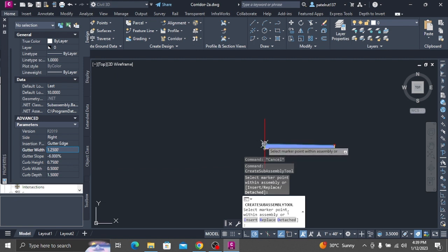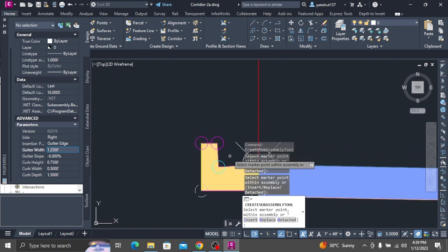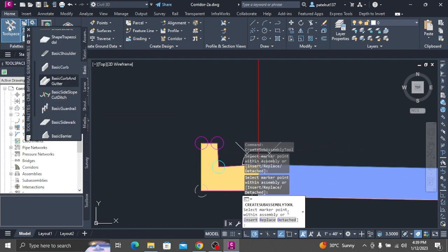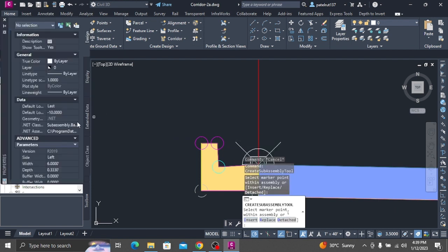Click OK. Specify the fixed lane horizontal target. In the Baseline and Region Parameters dialog box, click Set All Targets. In the Target Mapping dialog box, in the Transition Alignment row for Basic Lane Transition, right-click the Object Name field. In the Set Width or Offset Target dialog box, specify the following parameters. Select Object Type to Target, Alignments. Select Alignments, right, 1. Click Add. Click OK. Specify the Transition Lane Horizontal Target.